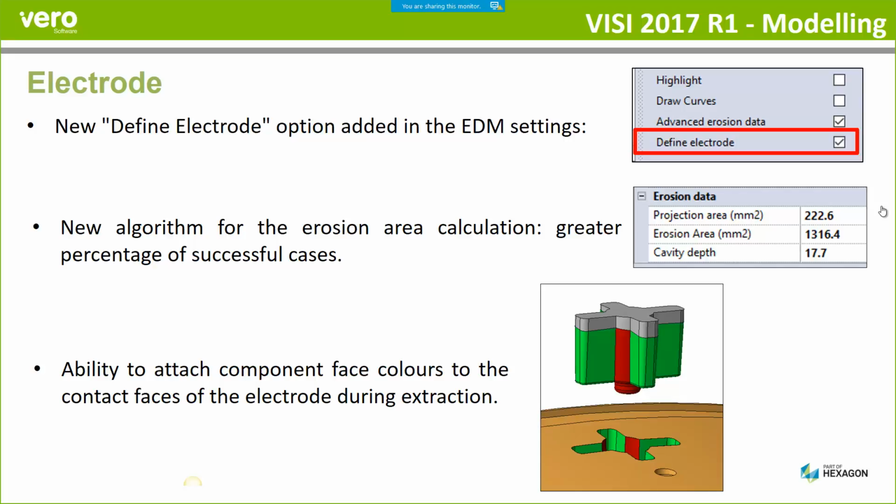So it'll automatically move it to an electrode layer, automatically add in an origin for the manufacturing of that electrode, and you can then link that electrode geometry to your electrode manager. It doesn't look much, it's just a tick box, but it's got a useful function if you're handling data from other sources as well.